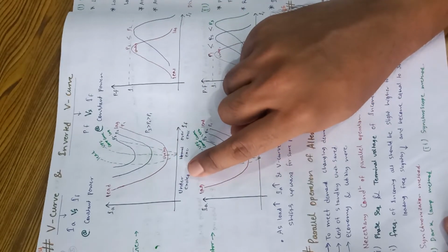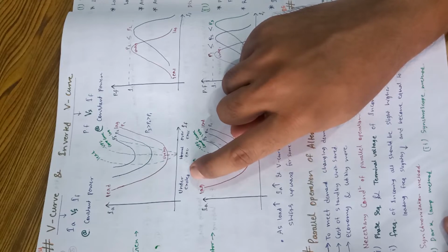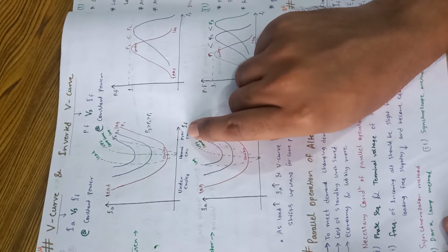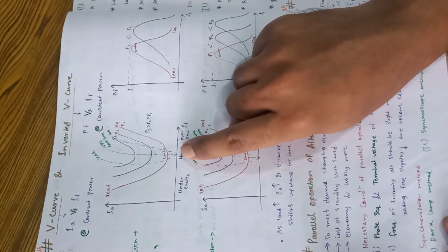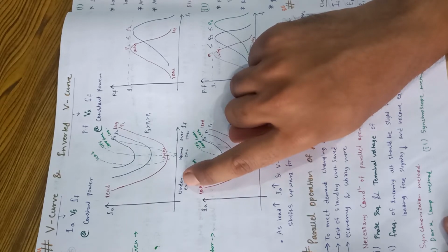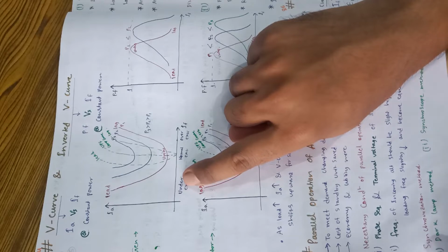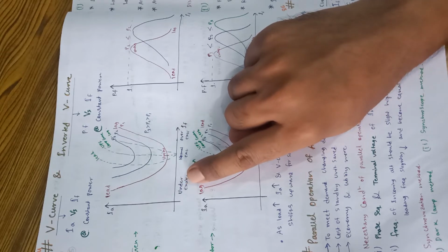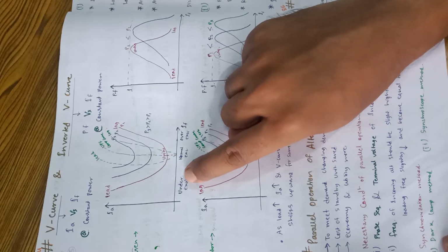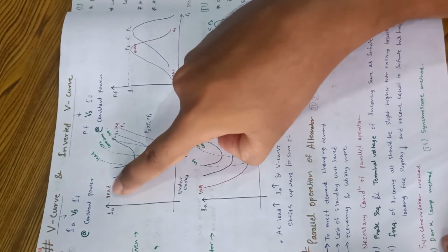When field current IF is less for a generator, it is under excited; when field current is more it is over excited; between these it is normally excited. For an under excited generator, the generator will take reactive power, meaning it takes lagging current, which means it gives leading current. Giving leading current means the generator is working at leading power factor.